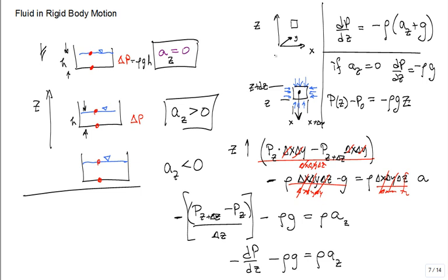And so I start my coordinate system at z = 0. I move up, up, up, up, up. As I move with increasing z, I've left off the z right there. No, I put it right below. Right there is my answer. What happens? The pressure goes down as I go up higher and higher in the fluid, in a stagnant fluid. True or false? True. So that confirms what we just said. We start here, we go down, it goes higher, increases pressure, etc.